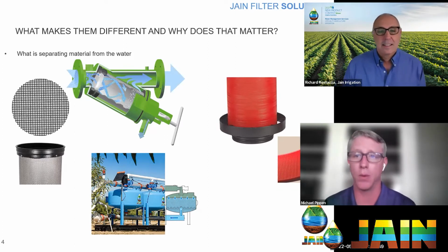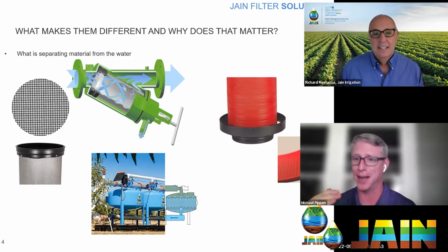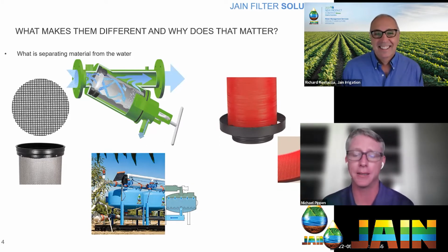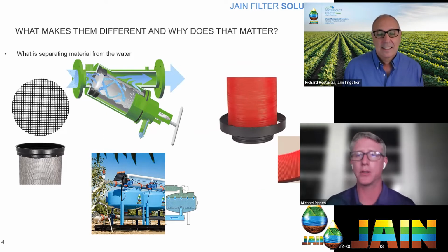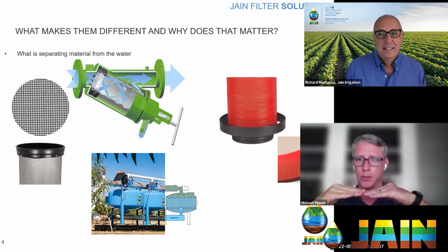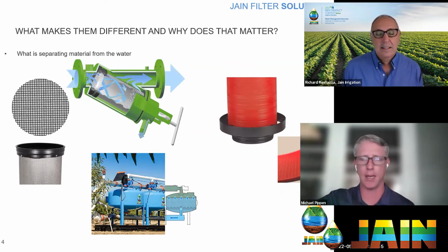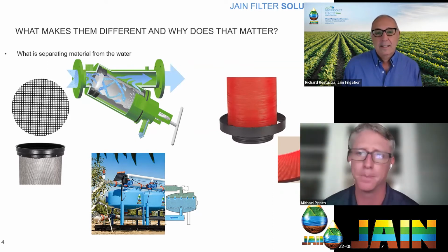It does work. It'll actually grab sand and sediment. This sand can be used to filter out sand and sediment, and often is in a lot of our applications in the central U.S. on subsurface, and also out in California. So that's how it works. It's a very specific sand. That's one. And two, there's also some sort of barrier or screen mechanism at the bottom that keeps our very specific size sand in the tank and keeps it from going out to the field.